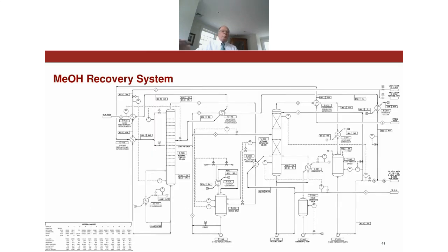So that system replaced an old distillation system that was built for a different purpose. It was repurposed. It was not the right metallurgy, and so the equipment that it replaced was corroding. There was enough sodium chloride present in the feed to cause stress corrosion cracking. So in the new system that we supplied, we made the stripper all out of duplex stainless steel so that we wouldn't have that issue again.